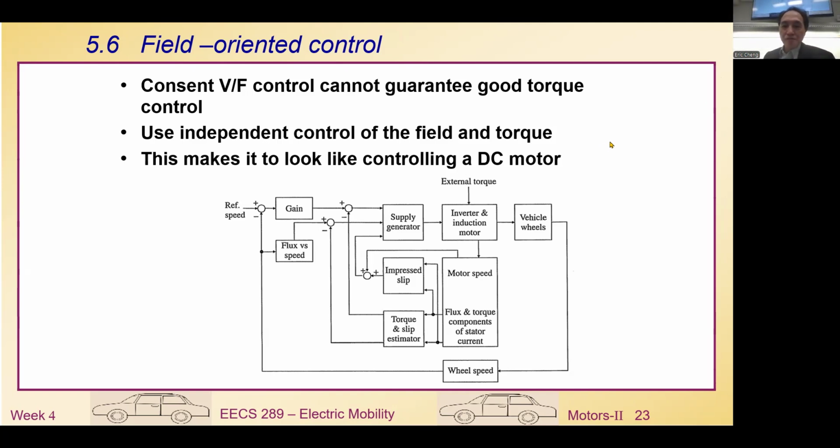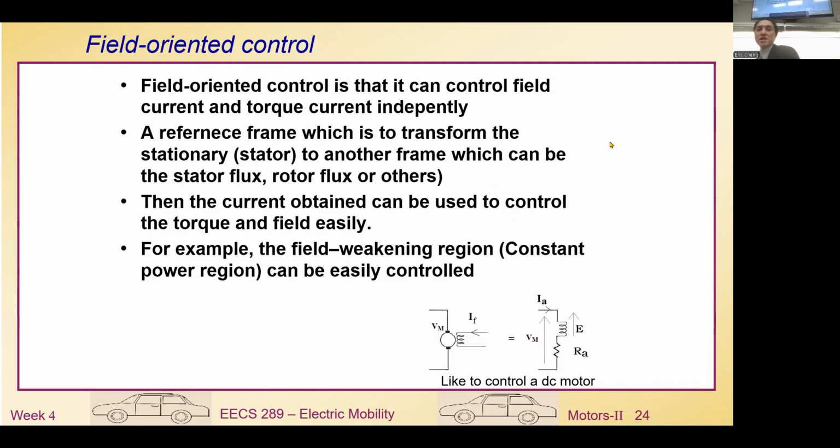After this, the next thing we look into will be the field control. You can see that in this control, we basically have a motor here, trying to make the FOC control look more like a DC motor. That's to say, we're able to control the field current to the field winding and also the armature current. So that means with FOC, although we try to control an AC motor, actually we use the DC motor method to control the FOC system.